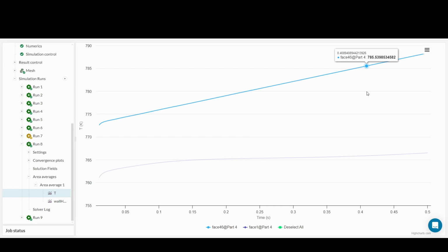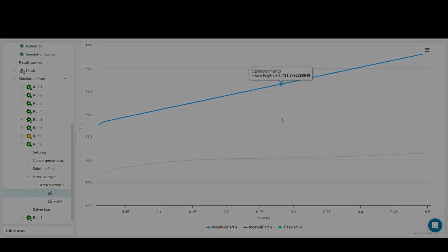There's also a paper, I'll, if I remember, put a link in the description, of just using basic shapes, the expected convection coefficient for different shapes, combining them. It's a pretty good paper where if you don't have CFD, you can use that to approximate it, get somewhere close to use in simulations.